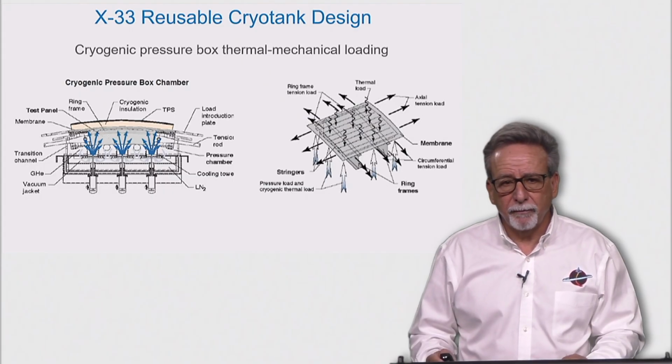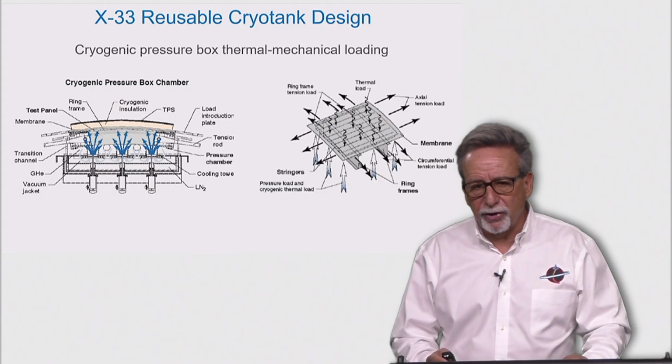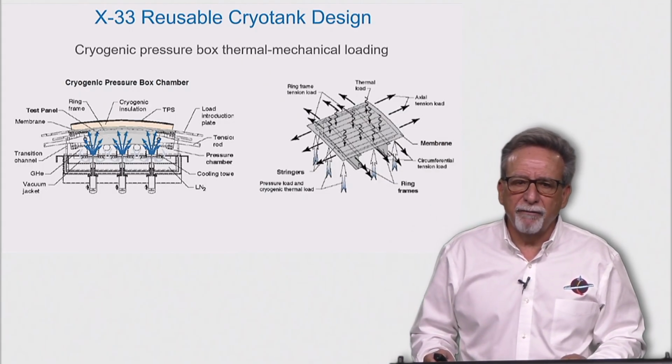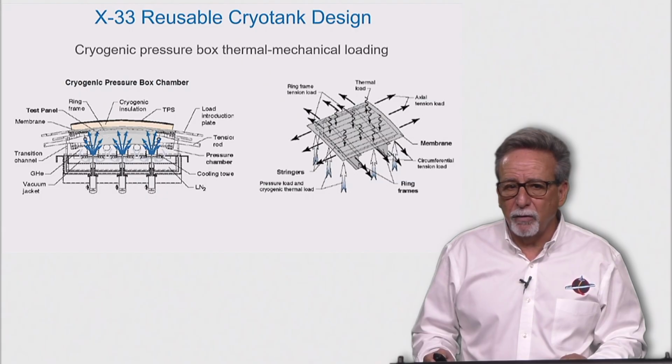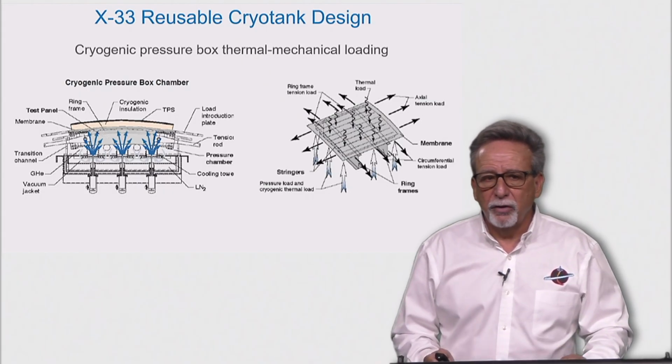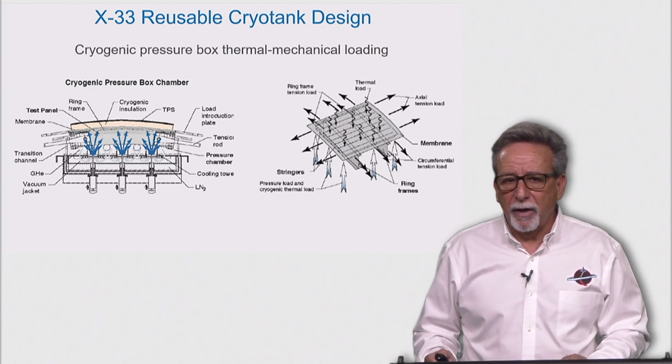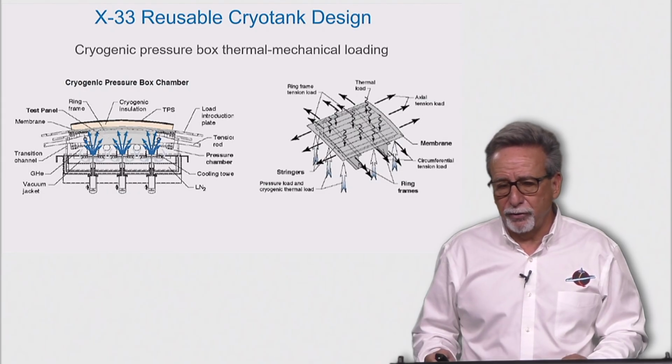The vacuum-jacketed pressure chamber can withstand internal pressures ranging from about 372 kilopascals using gaseous helium as the pressurization medium. Test panel and chamber can also be subjected to internal temperatures ranging from 250 Fahrenheit to minus 450 degrees Fahrenheit with the aid of 12 copper heat exchanger towers that are encircled by copper coils that contain liquid helium, gaseous helium, or liquid nitrogen.